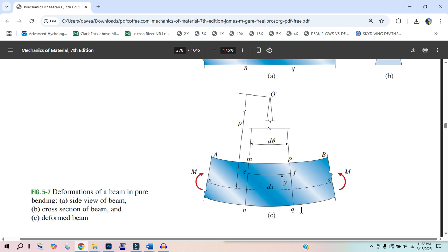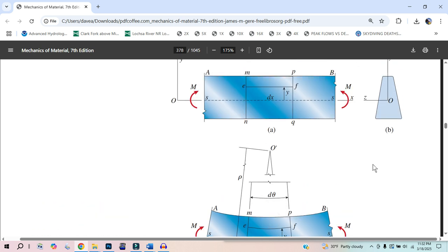Visual change in length, we're in tension, that requires we can get a number on the stress, and then we can go back to this diagram and say, I do know the area right there. I'm just going to circle this amount of area, and if I know that pressure and this area, pressure in pounds per square inch, area in square inches, I'm going to multiply those two numbers together, and I can know the force right there.